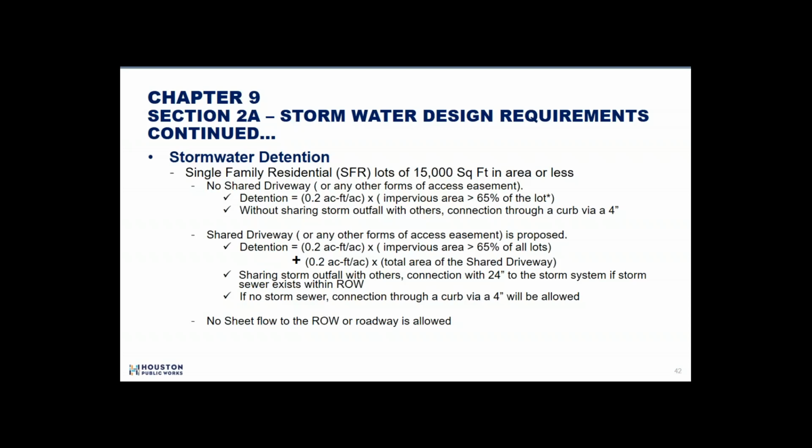Now, shared driveways are what is different. The equation you see up here means that we are going to require that the shared driveway, the entirety of it, be captured. So the 0.2 will be applied over the entire shared driveway, and then the remainder of the lot will be calculated at whatever's greater than 65%. So hopefully that will add some clarity to the issue.